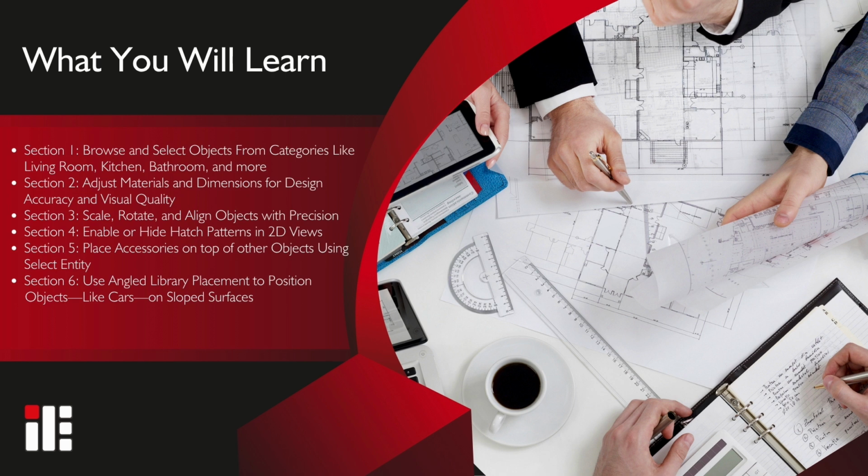In this video, you'll learn how to place and customize library objects in ideCAD Architectural to enhance your interior layouts. We'll guide you through browsing the object library, adjusting object dimensions, scaling with or without uniform ratios, and rotating objects during placement. You'll also learn how to control hatch display in plan view, place objects on top of others using the Select Entity feature, and use angled library placement for realistic alignment on sloped surfaces. By the end of this video, you'll be able to efficiently furnish your architectural plans with detailed and well-placed 2D